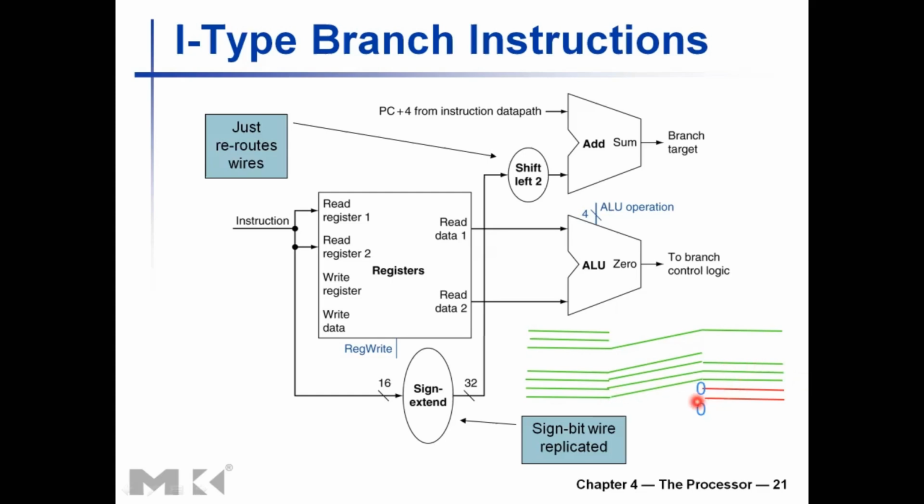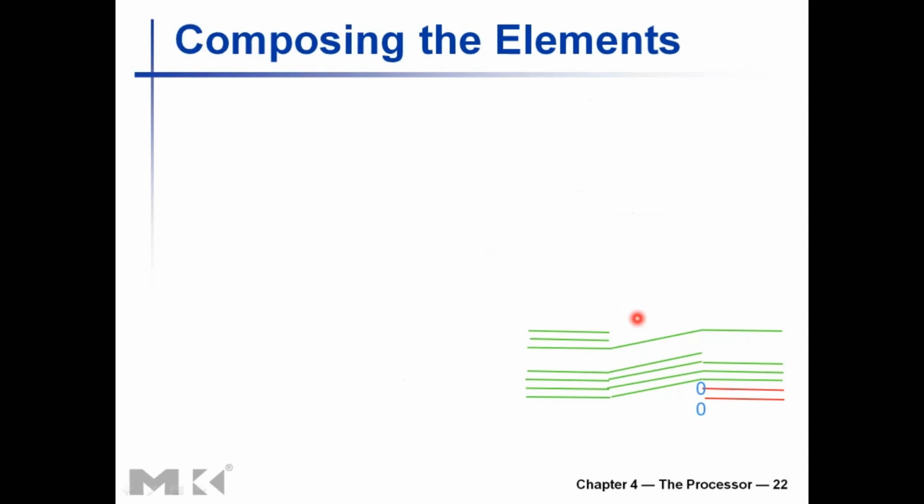So it is like you did the shift operation, but you don't really need a shifter because we are always shifting to the left by 2 logically, filling with zeros and discarding the 2 most significant bits coming from this 32-bit signal here, the sign extender. So you can just reroute the wires like this. I hope that that is clear. You don't need a shifter hardware. You can hard code it like this. Right. So I only have a little bit more to cover today. Let's go to the next one.